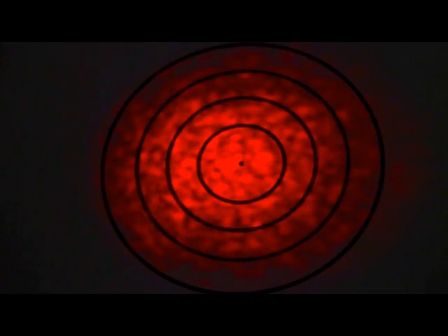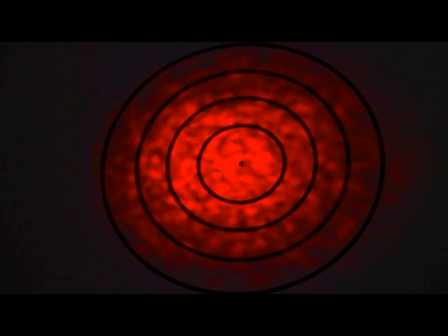Now let's try an experiment. Let's try to see if we can see what happens with a mandrel wrap, the same mandrel wrap that we use when we control the mode power distribution in multimode fiber for testing. Now notice that there's a significant amount of light still outside the second circle, but that the outer circle encompasses almost all the light.